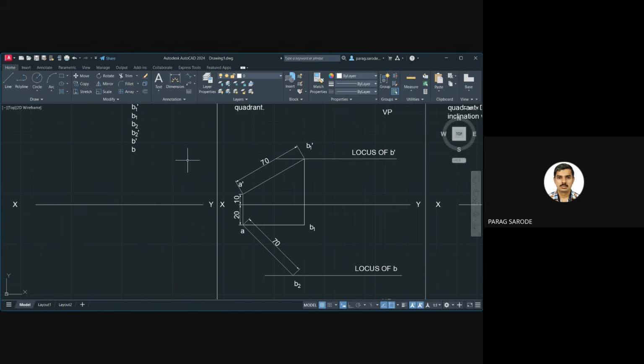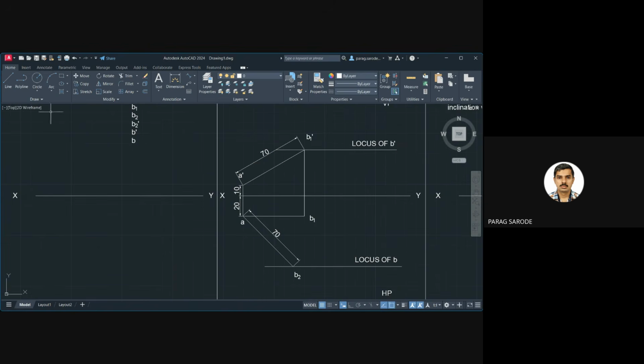Now the same we will do for the B2 point. We need to project it upwards. Now the same question: B2 dash, till where? Till it meets the horizontal line passing from this A dash. So I'm doing it in one step. You can draw the horizontal line, let it intersect, then trim the portion. Now this point, brought above the X, is B2 dash.